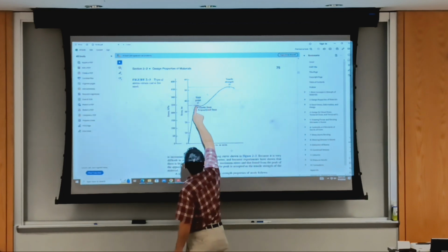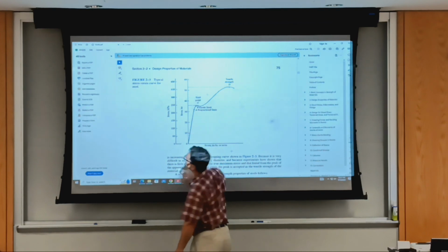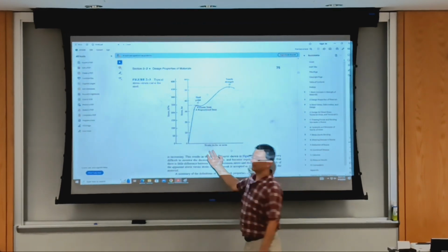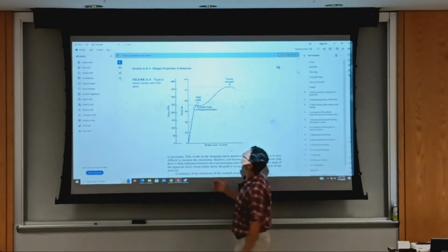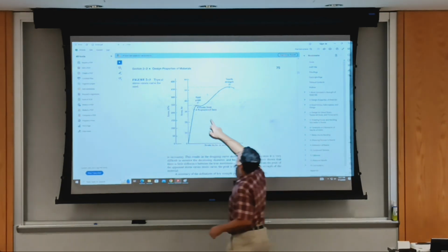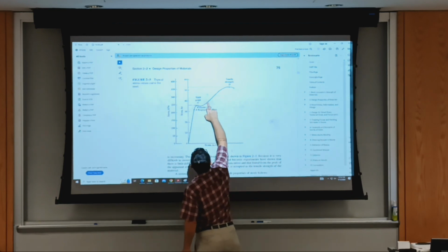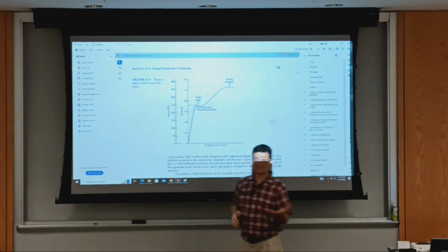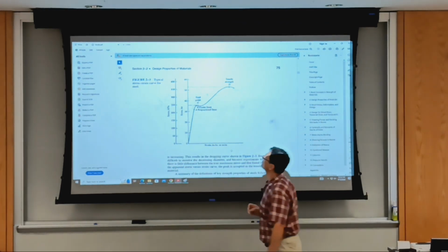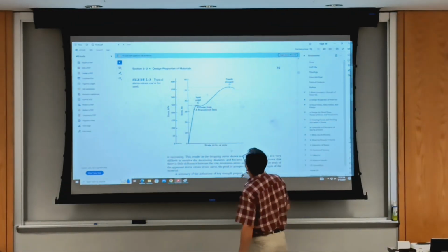And then past this point, some materials have this flat region, little change of stress but a lot of strain increase. Not all materials behave this way. Not all ductile materials do, but some have this visible shape. You continue applying the load, and you keep dividing by the same initial area and calculate the stress, which some call engineering stress. In manufacturing processes, we call it engineering stress. And then there's a true stress.